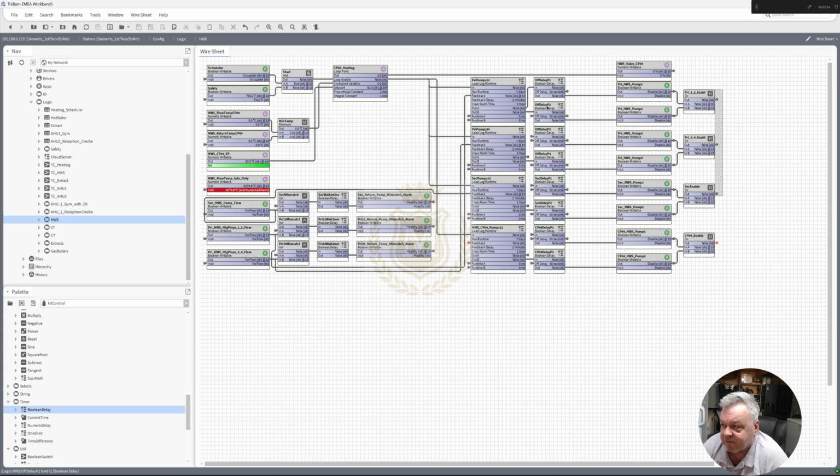If this one starts immediately, say we're running pump 1 and pump 2 starts immediately, they will both run together for 30 seconds, but pump 2 will carry on running. But if we've got an emergency stop, this will still carry on counting the off delay of 30 seconds. So what I wanted to do is, if someone hits the emergency stop, we actually stop this counting. And the easiest way that I do that is by putting an AND gate in its output, and that's what I'm doing at the moment.